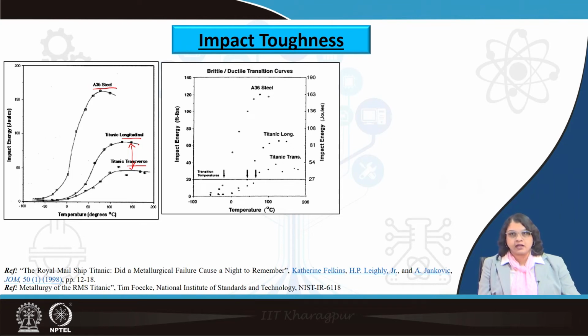As I mentioned, anisotropy in the properties is never good news, which means that it will serve only as the worst possible case. We do not know at the point of service which way the loading will come. So, we want to have quite uniform properties throughout, otherwise only the worst properties will take the lead, and that may lead to early fracture.